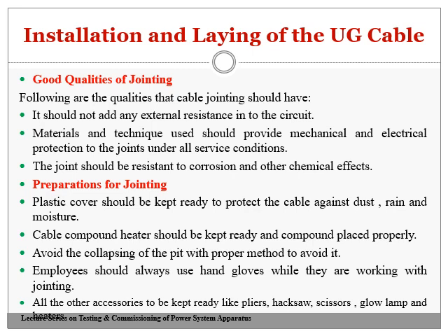The employee should always use hand gloves while working with the jointing. That is the precautionary measure, the safety of the personnel should be done as such. All other accessories should be kept ready, like pliers, hacksaw, scissors, glow lamp, and heaters. All the accessories which are required should be kept ready before the starting of the jointing.